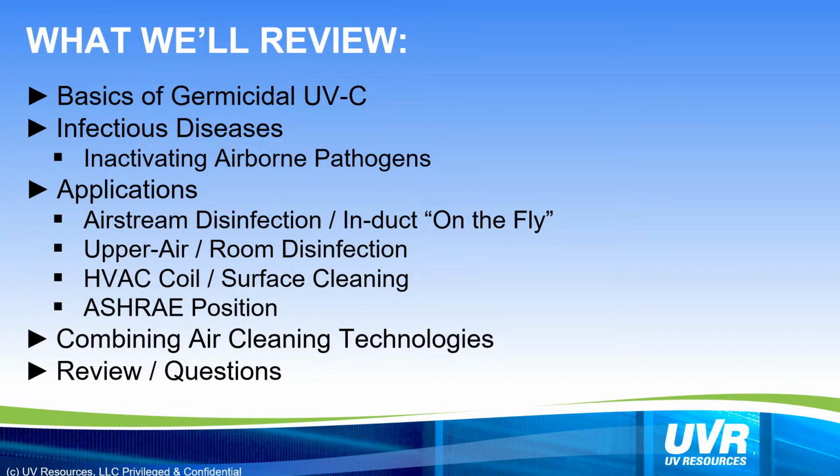Today we will talk about the basics of germicidal UVC and specifically how UVC energy can inactivate airborne pathogens. Infectious disease experts and building science professionals recommend 3 scientifically proven means of reducing pathogen spread: ventilation, filtration, and germicidal ultraviolet light systems. So UVC is one of 3 engineering control strategies that scientists and building engineers endorse to reduce infectious diseases.